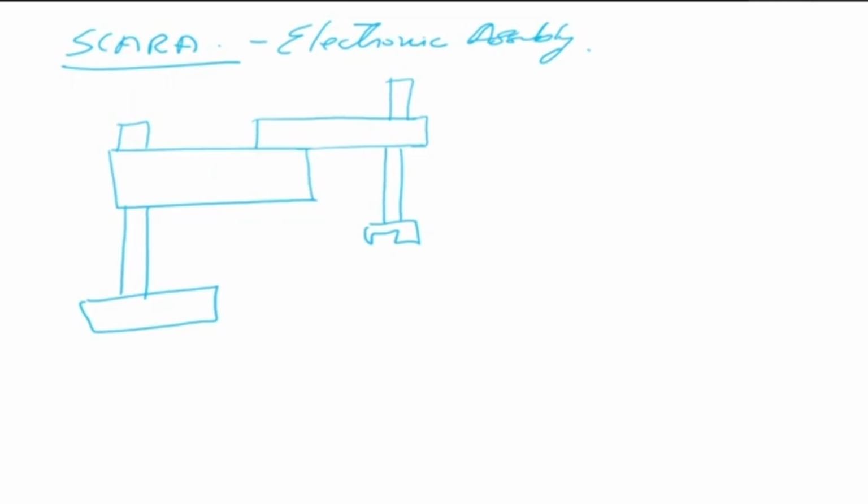Now we'll assign the DH parameter table. First we assign the axes as per DH notation, then we assign the DH parameter table, make the table, then take each row of the table and make the corresponding frame to frame transformations. So first let's look at how this moves. This is my first axis, a rotation axis. This is my second axis, which is also a rotation axis. The third axis is a prismatic axis, which is translating, and the fourth axis is a rotation axis.